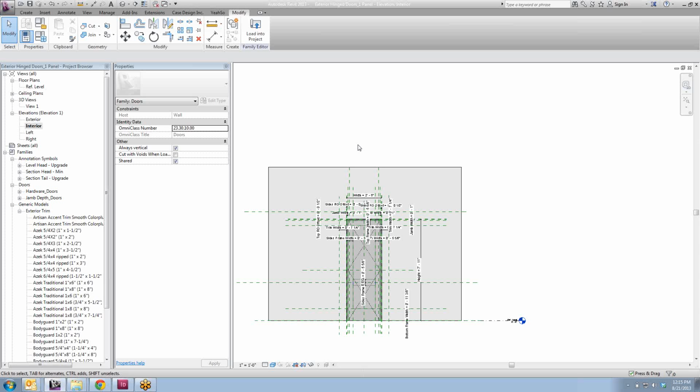Not really. So let's say you're putting a door in a wall, but it's a doubled wall because it's a connector next to a garage or a connector next to a mod, right? And it's doubled up, and that's just how we do it. The overall thickness of the wall is like 10 inches. But you wouldn't order a door with a 10-inch jamb, right?